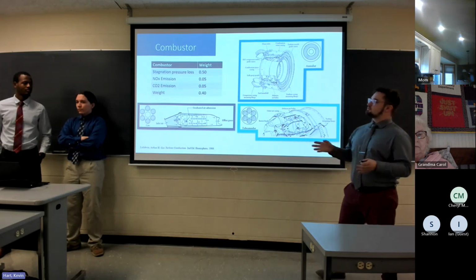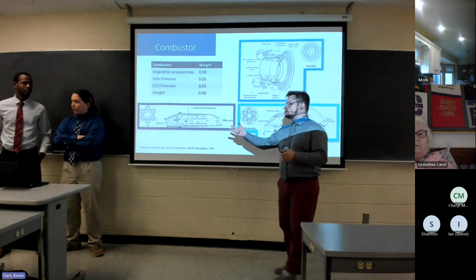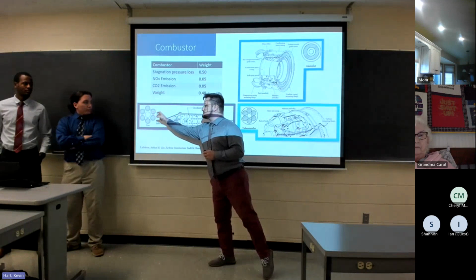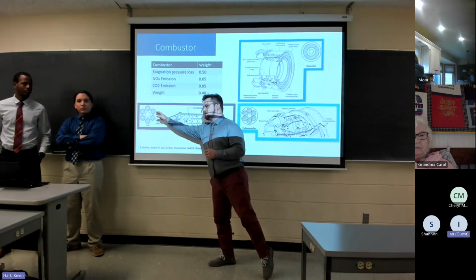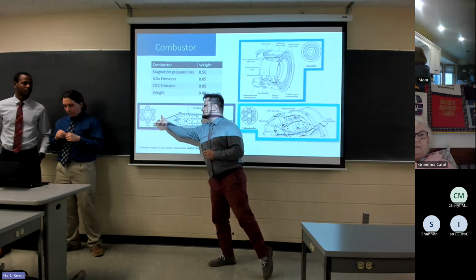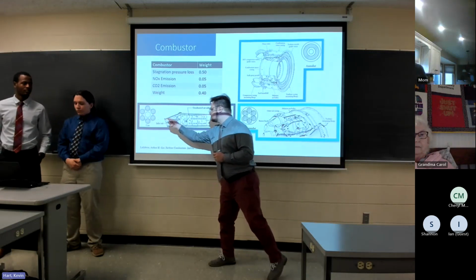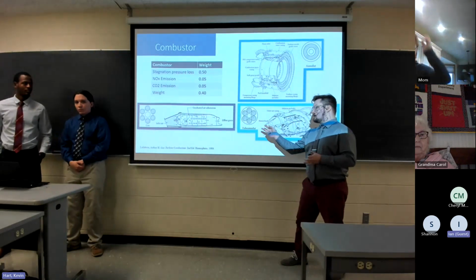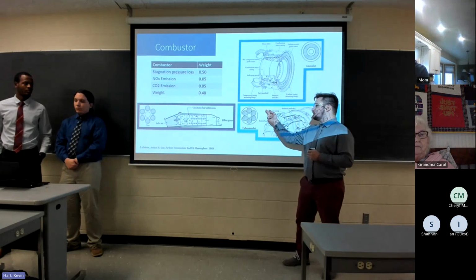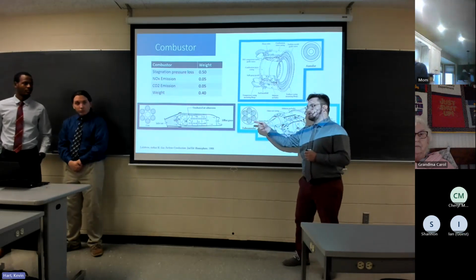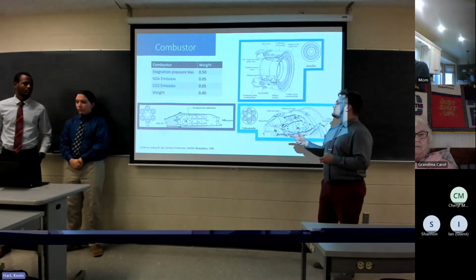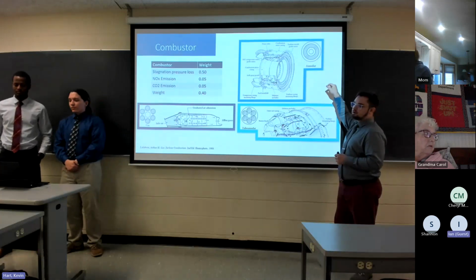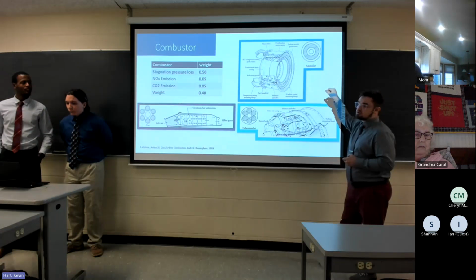The can type of combustor is the design that was first introduced, and it is composed of mostly a casing, specifically around a liner, and then burning within that. It has essentially separate ignition sources within each can, and it is composed of large ducts to each can. The turbo-annular was next in development, which is a large casing around several concentric liners, each with their own individual ignition source. And then the most recent modern development is the annular, where it's a concentric ring of casing and liner, and then interconnected ignition.